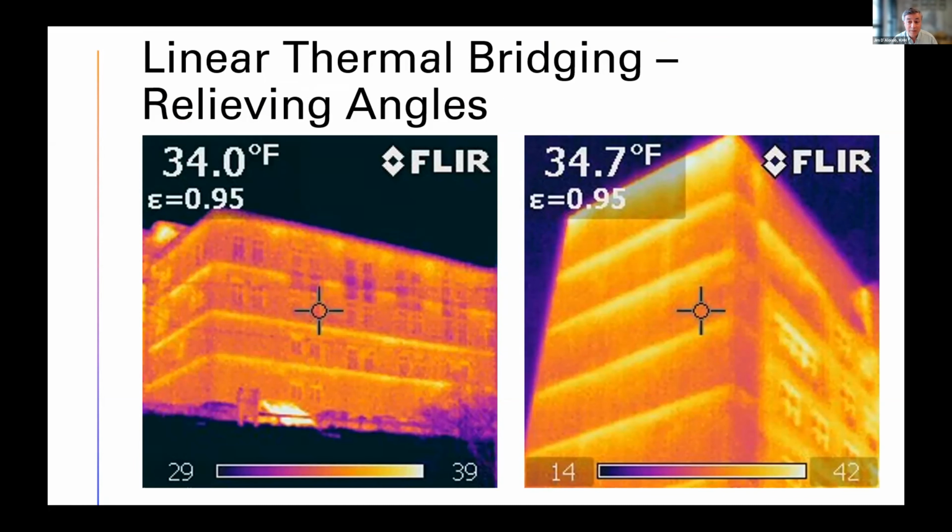Get yourself an infrared camera. They're cheap. They're 10 times as cheap as they were when I took these pictures 13 years ago, and Rob and I were commiserating over them. These aren't Rob's buildings either, by the way. These are shelf angles, or rather the warm brick adjacent to the shelf angles that represent continuous problematic thermal bridging. The mechanical engineer and the architect didn't anticipate the tremendous heat loss that we see.